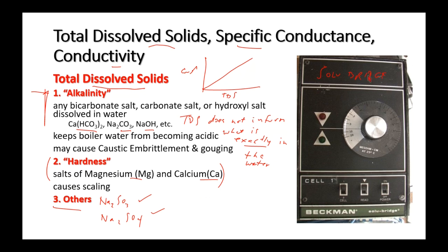which is a really cool, old school piece of equipment. And basically, it's got a red light, and it's got a little green light. I won't mess it up with my pen. And it's got a scale, and the scale says megohms per centimeter at 25 degrees. What we'll do is you'll have it in microsiemens. And this here is like 1959 technology, but don't be surprised if you still see it in your plant.